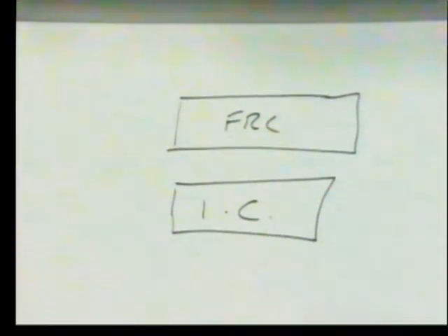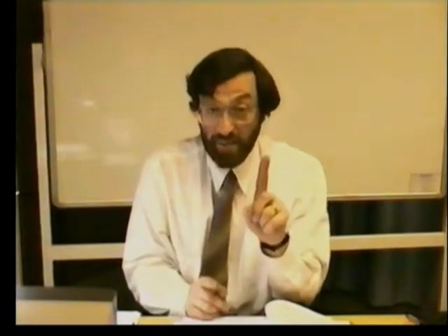And what the input capture register is, it combines the idea of a free running counter with an interrupt. It still issues an interrupt. When the interrupt occurs, a signal is sent to your processor to say stop what you're doing and service me. But it also takes an instantaneous copy of the time that the interrupt arrived. And that means that even if you're delayed in executing your interrupt routine, you can always go back to the copy that was taken. It's like having a log. The interrupt occurs, the time it occurs is written for you into another memory location.